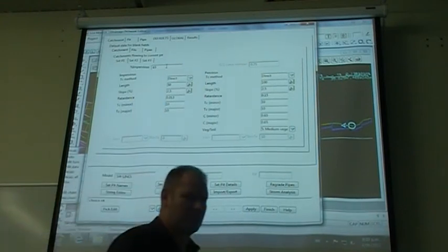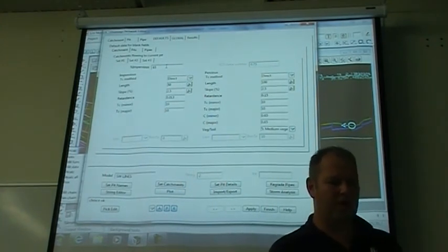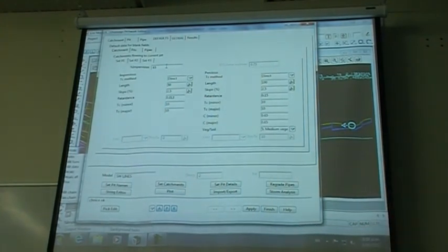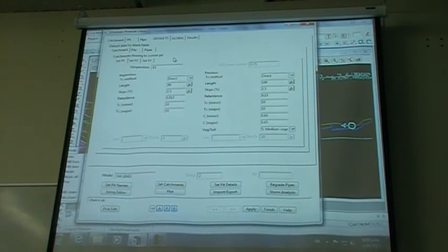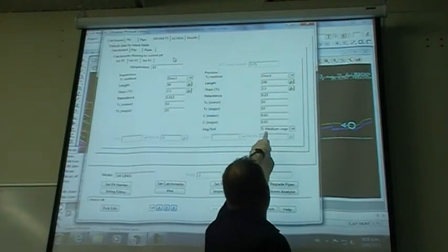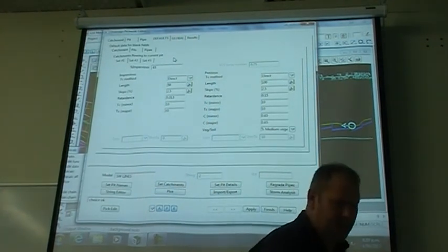So all our times of concentration are 10, and all of our storm durations will be 10 minutes. At this stage we're just filling out the defaults. So times of concentration need to be changed to 10 minutes, and make sure all our C factors and percentages are set at 65.